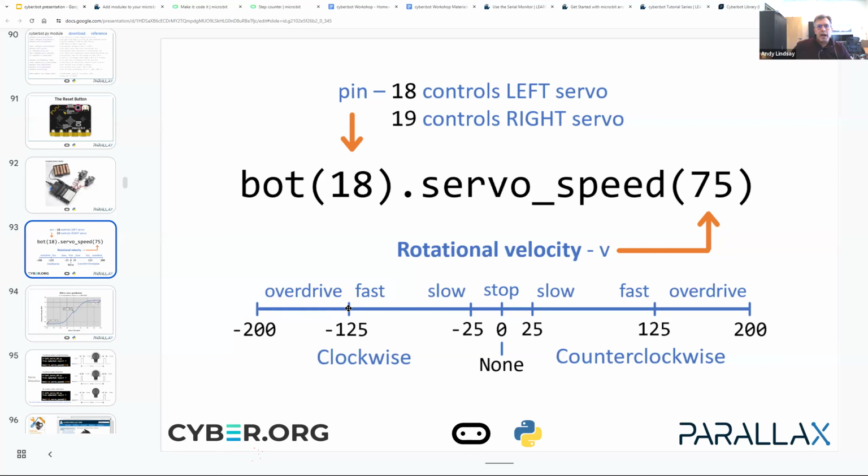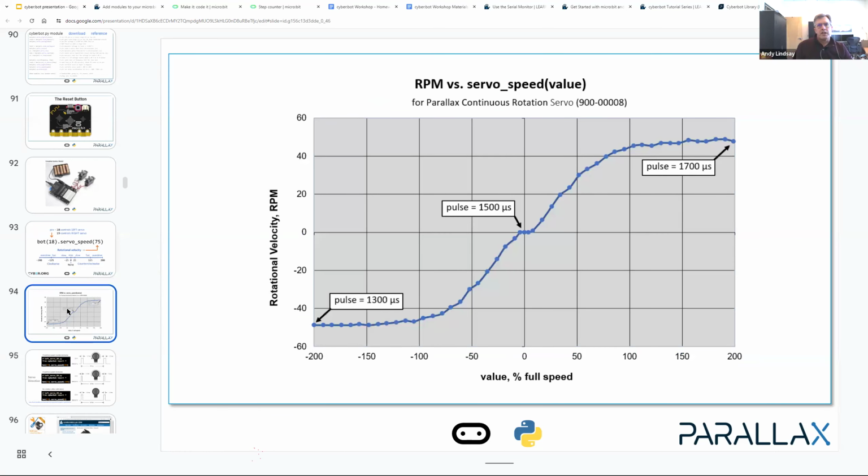And so if you have it at 115, you can slow down. You'll also notice that it won't go perfectly straight, even though you have identical values. So you'll need to slow down a faster wheel to straighten out the path of the bot. And we'll get to play with that on Wednesday.